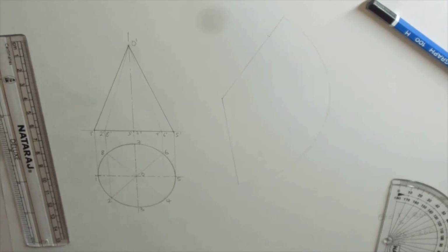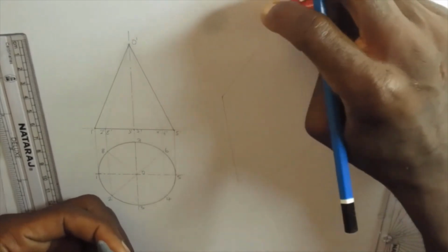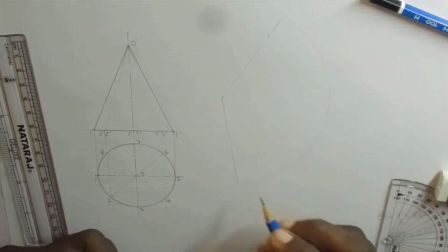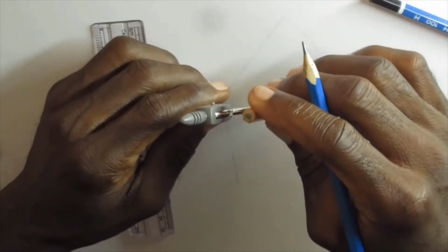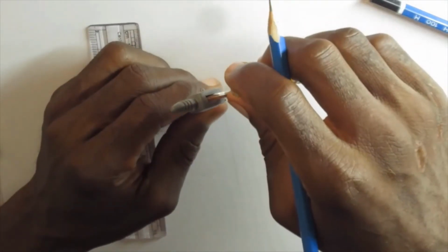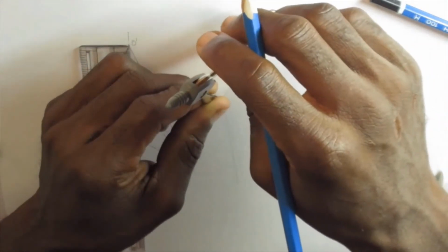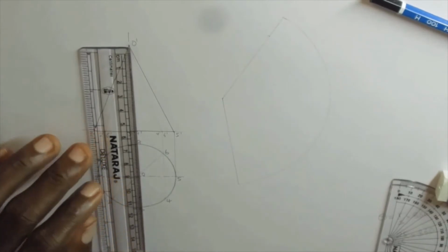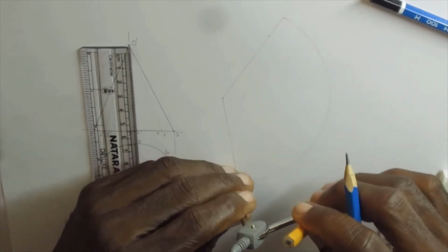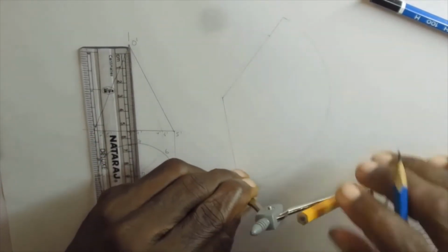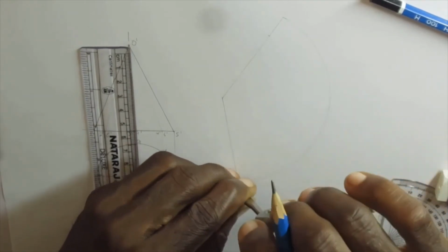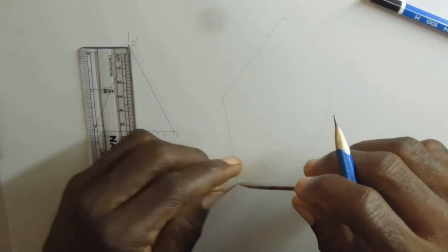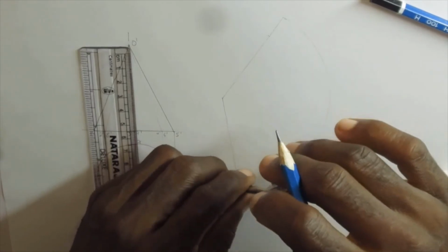then we draw the other line. So we have now the area through which we're going to have the developed cone. And the next thing is to divide this arc. That angle we are having, we need to divide it into a given number of equal parts, which should be equal to the number of parts we have divided the base circle of the cone, which is 8. So we need to divide this into 8.